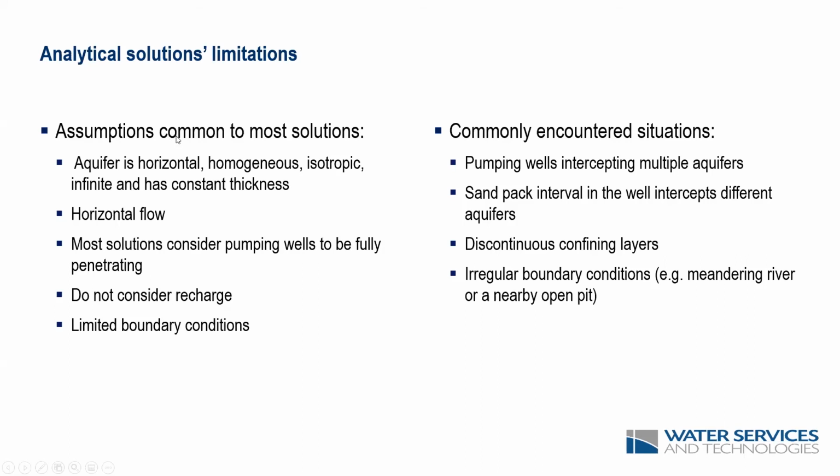Assumptions that are common to most of these solutions are that the aquifer is horizontal, homogeneous, isotropic, infinite, of constant thickness. Horizontal flow, and pumping wells are considered to be fully penetrating the aquifer. They do not take recharge into account and also have limited boundary conditions that they can consider adequately.